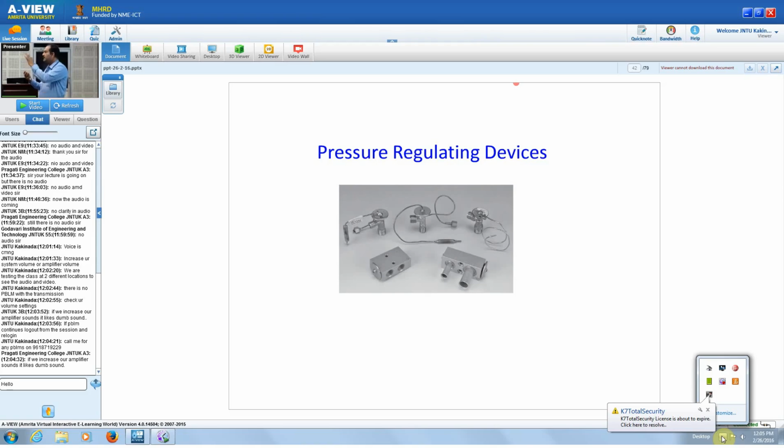If you put a pipe on your mouth and blow, then it is a pipe. Of course, the discharge may be different. When you calculate the discharge using the orifice and using the mouthpiece, there will be a difference, because if there is a length, definitely some loss will be there, because some pipe friction will be there. Right? That's it.